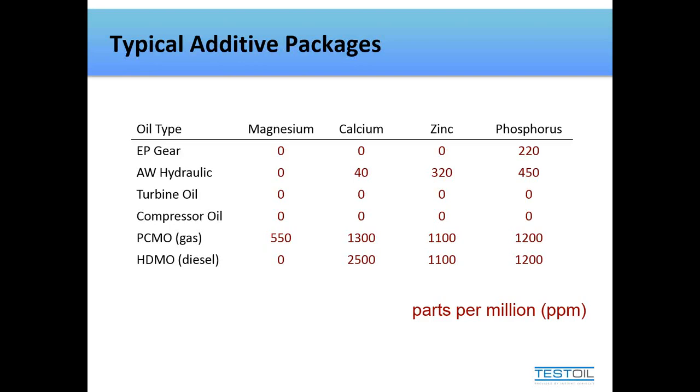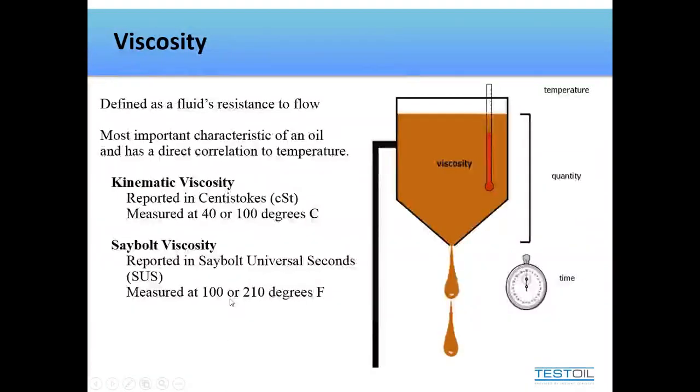So when you get your report and you'll see I have a gearbox, and you look at the data to see actually what additives are showing up in this actual gearbox on your report. Well, if you see, say, zinc and phosphorus, and you have, say, a 620 gear oil, it's more than likely mixed with something or something special, because you should just pretty much have a high level of phosphorus in it. A couple other things here and there, but you kind of get the idea. You really shouldn't see magnesium or high levels of calcium in your gear oil. So right off the bat, that has some value when you're actually looking at your reports to see if, hey, is somebody topping this off with, say, motor oil, or are they putting the right oil in it? That'll kind of aid in finding out what you got.